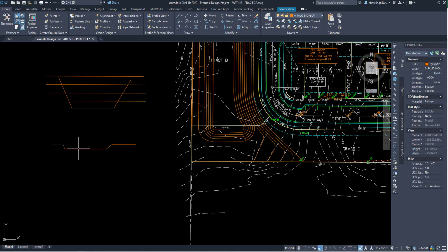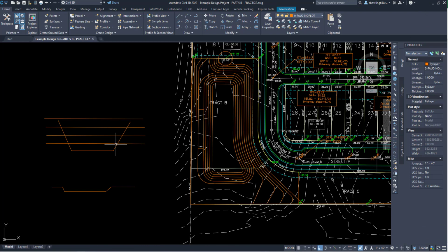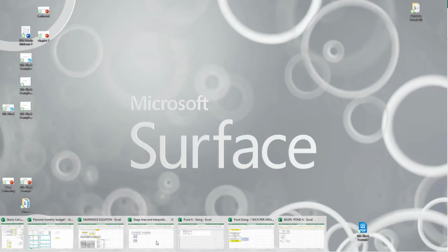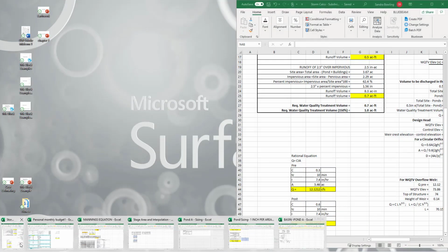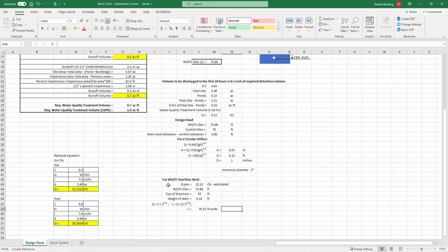Okay, so water would just overflow this weir, and so that's what we're going to go with in this design example. Now this doesn't always work out because of stage discharge, but it gets you a first impression idea of what the weir equations and the orifice equations basically look like, and the assumptions that we use.